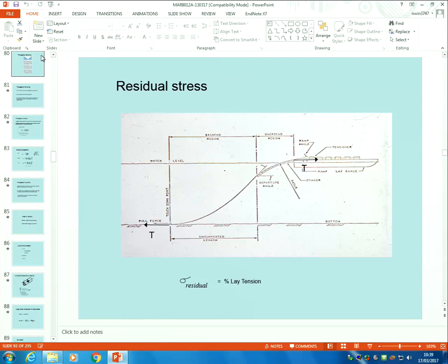I mean, plane strain or plane stress means the stress or the strain stays constant across the section. But when you do thick wall, it obviously can't. Say plane. Yeah, but I'm just curious about even for the thin wall, but if it is under very deep water, where there is external pressure, and because of that external pressure, this thin wall cannot expand. And then in that case, it acts like a thick wall pipeline because of the restriction.